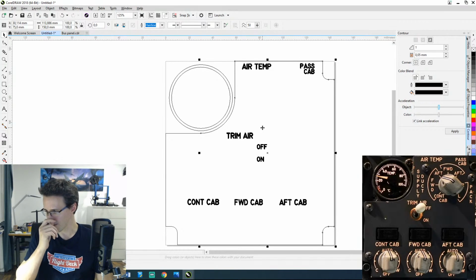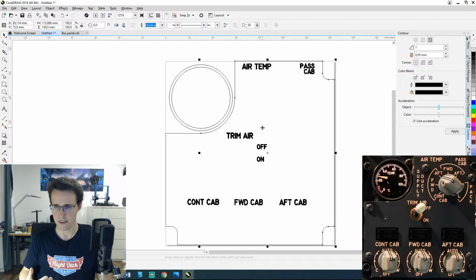You have to ensure that you have an exhaustion fan, so you can suck out all the fume that appears when you are lasering, and working with the CNC is really easy.